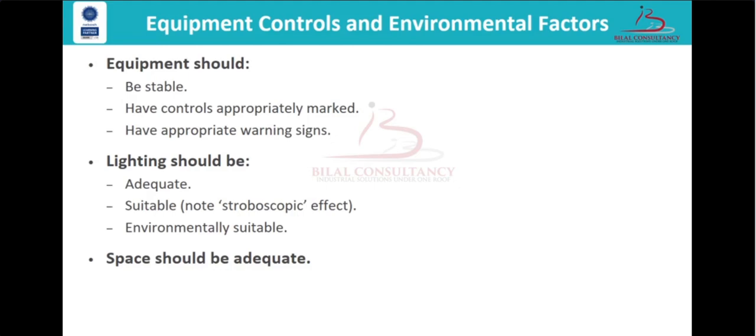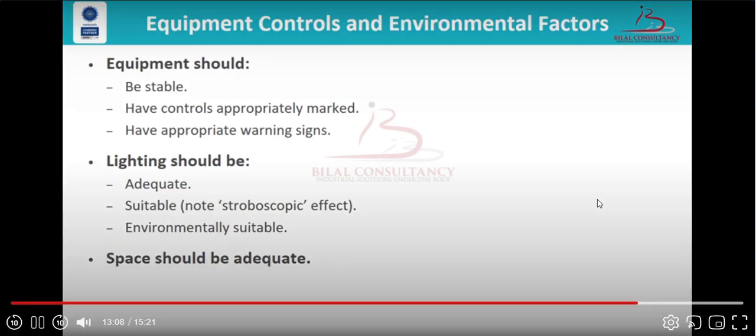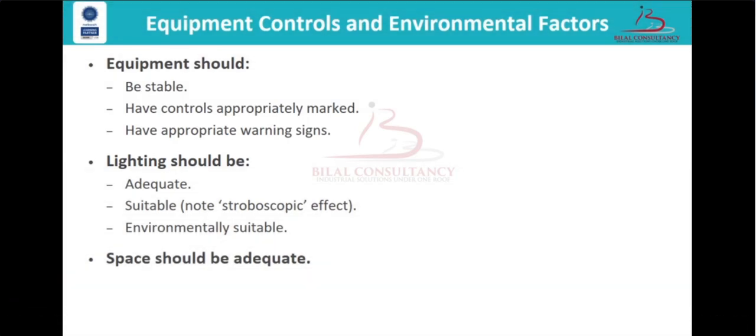Moving forward towards the lighting consideration, when using any kind of equipment, adequate general workplace lighting should be provided around equipment for the safety of both operators and others in the vicinity. Local lighting such as spotlights positioned above machinery might be required to give higher levels of light in critical areas. Lighting should be suitable for the type of equipment in use.